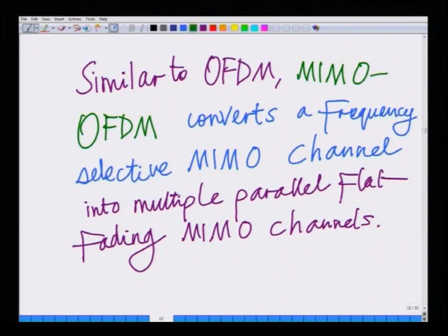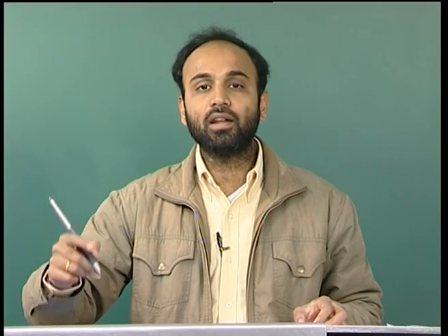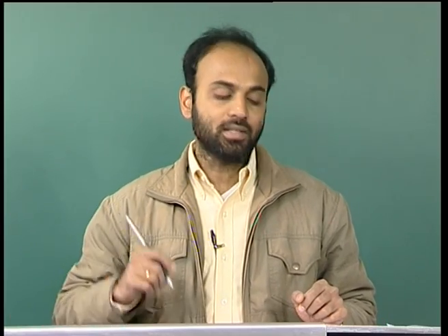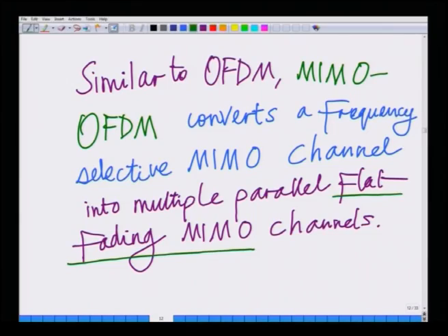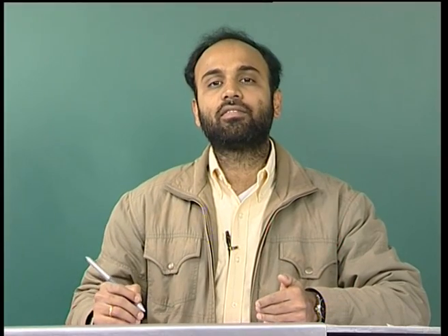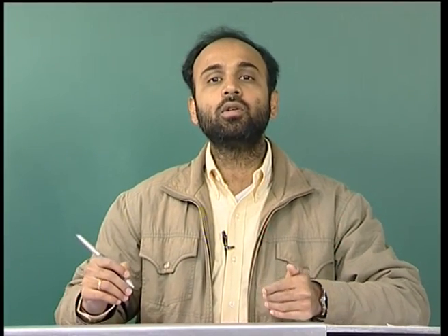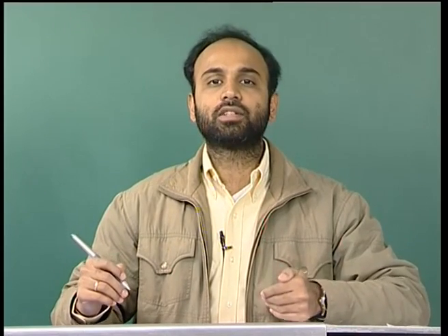The key here is the flat fading MIMO channel, thus simplifying receiver processing. Now, in the absence of a flat fading MIMO channel, one needs to eliminate MIMO intersymbol interference,